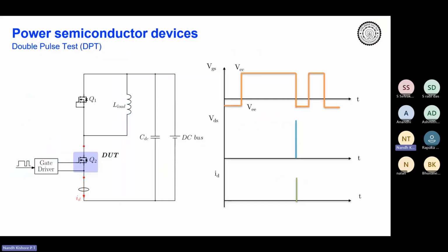That is why over here as well, you can see that VEE is not exactly at 0. It is at a negative value. And your threshold might be somewhere over here, but we are not driving the VGS at threshold voltage. We are driving it at a much higher value, right? We will see why in just a few slides.